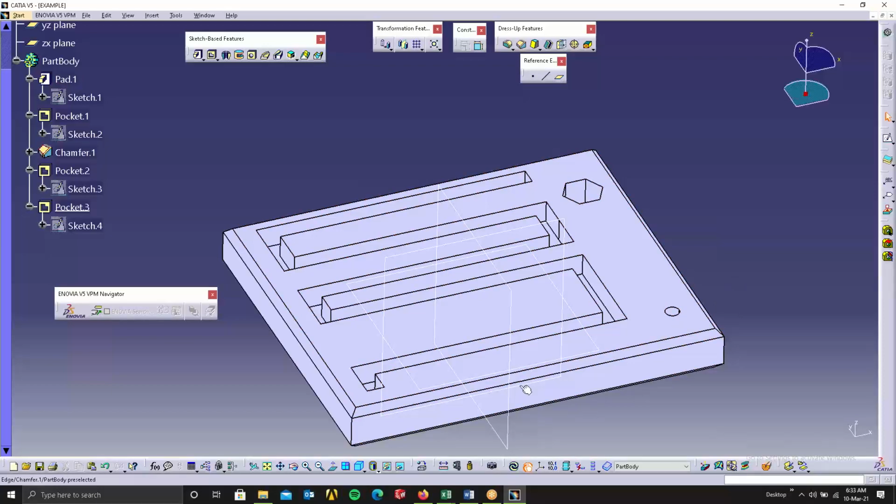Running a chamfer here means you have to put this side, then clamp it. Then 30 minutes will go. Then you rotate it and clamp this, 30 minutes will go, clamp this, 30 minutes, 30 minutes. So 4,000 rupees will be added here alone, and the backside again 8,000 rupees. This product would be only 5,000 rupees or so, but because of the chamfer it will become 10,000 rupees.